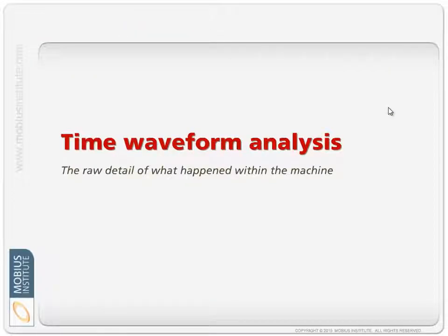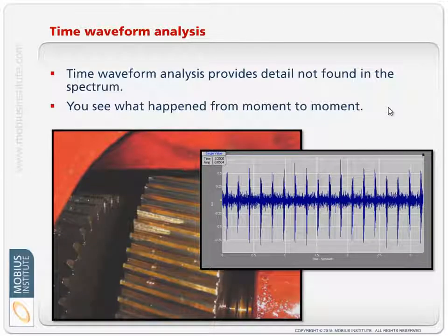Now, when we started all of this, I showed you a time waveform. We looked and saw it, and I'll show you that again just if you're not sure. The time waveform is more complicated to look at, but the time waveform can reveal all sorts of fault conditions that you might miss otherwise. So here's a time waveform, and I'll get back to what this means, but it's sort of like having a movie camera that's filming inside your machine and seeing every little thing that goes on as those balls roll around inside your bearing, as the teeth mesh together.